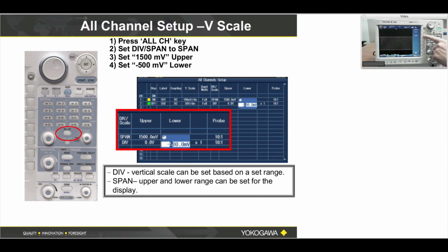And very similar to our previous exercise, you'll come in here and select where you want to save it. Press File menu button number 1, File List. You'll set the path here equal to USB, as we've done previously. I will hit Escape one time to get out of here. Soft menu button number 2 lets you name it with the keyboard editor.